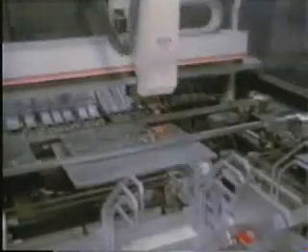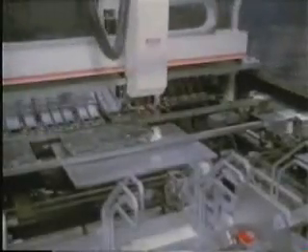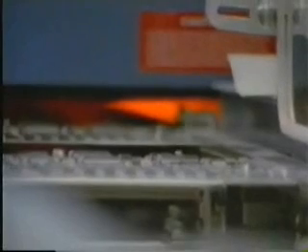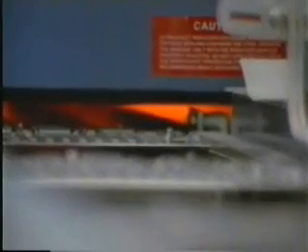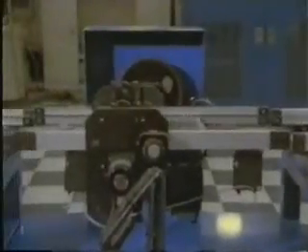Because of the various sizes and assembly requirements of the components, several different machines are used. Now the boards go through an infrared oven. The solder melts or reflows, binding the components to the top side of the board. Surface mount technology allows electronic components to be mounted on both sides of the board.